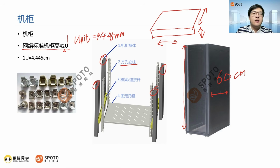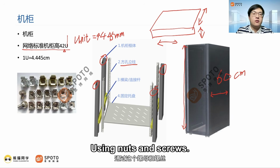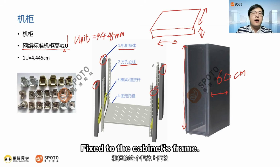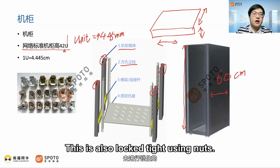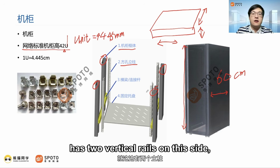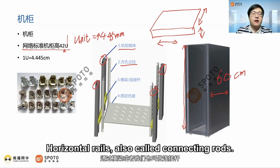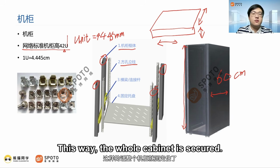The vertical rails are fixed to the horizontal rails using nuts and screws. The horizontal rails are fixed to the outer part of the cabinet frame, also locked tight using nuts. In this way, the whole cabinet has 2 vertical rails in the front and 2 in the back, using horizontal rails, also called connecting rods, fixed to our cabinet frame. This way, the whole cabinet is secured.